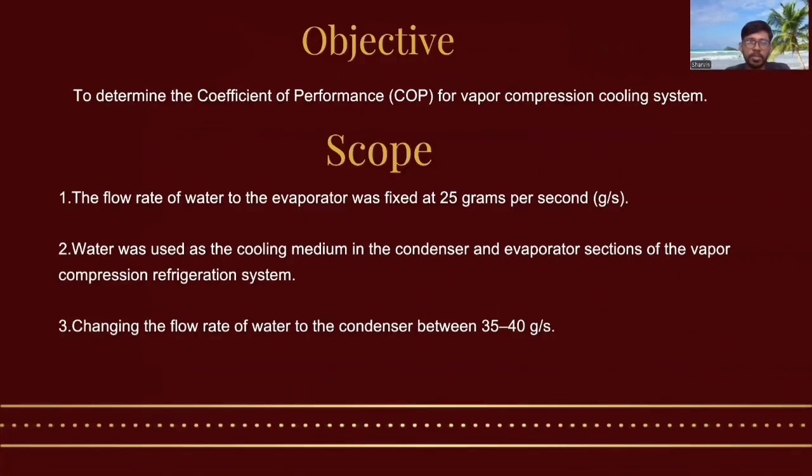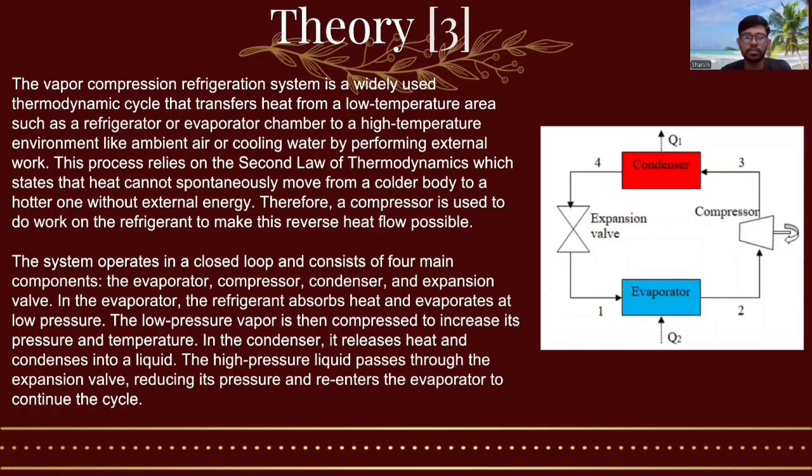Objective of this experiment is to determine the coefficient of performance, which is COP, for vapor compression cooling system. Scope for this experiment is the flow rate of the water to the evaporator was fixed at 25 grams per second. Water was used as the cooling medium in the condenser and the evaporator section of the vapor compression refrigeration system, and finally, changing the flow rate of the water to the condenser between 35 to 40 grams per second.